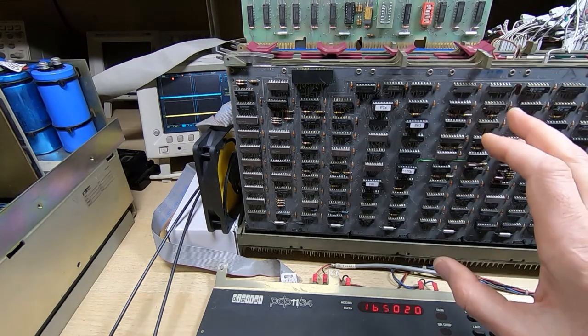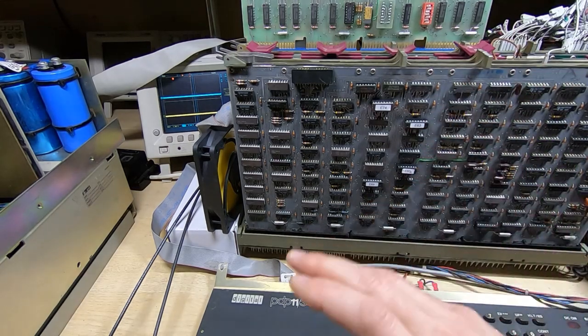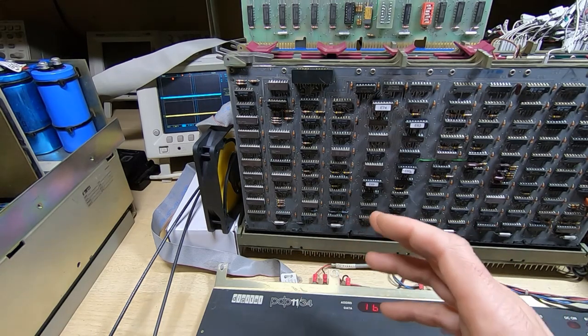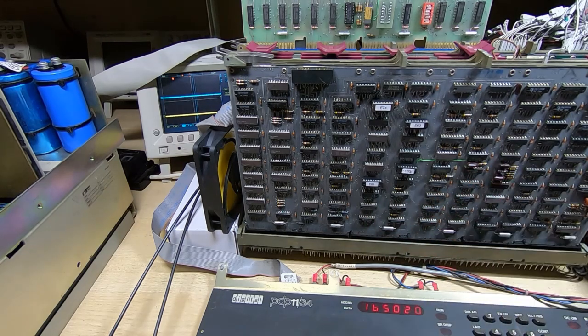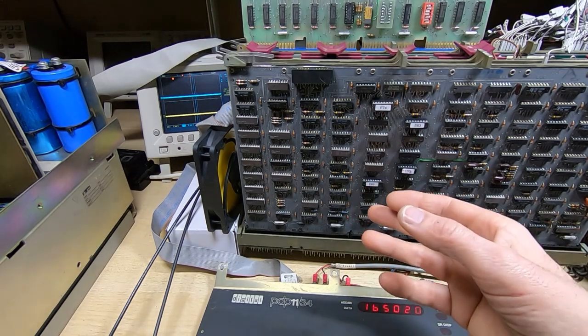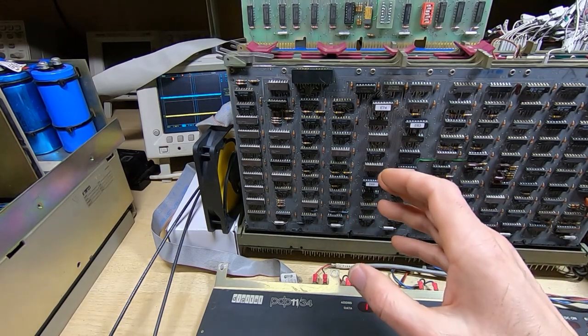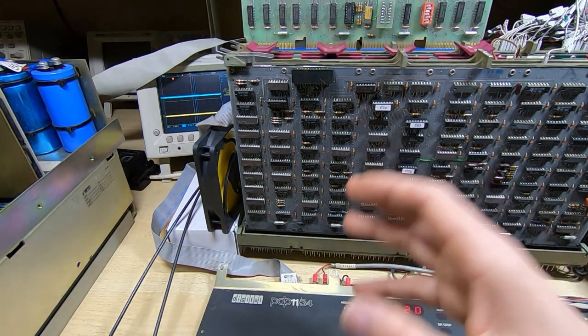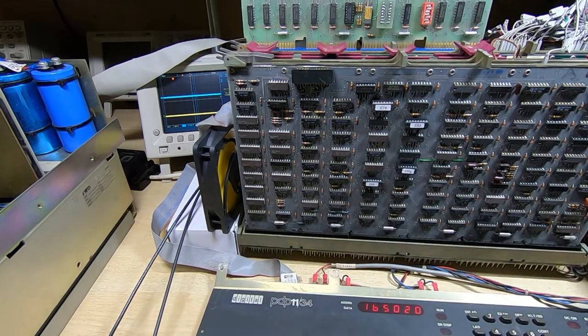So when you come to testing this, it's always best to use a scratch disk. You don't need a boot disk straight away, and I have a scratch disk in the floppy drive, so I know I'm going to corrupt the data on it as I go through the testing, so I don't want to risk a proper boot disk or a proper software disk. You could try write protecting the disks, but that's not really that successful, because whether the write protect works or not depends on how well the system's working. It might just decide to ignore the write protect and go ahead and write the disk anyway.